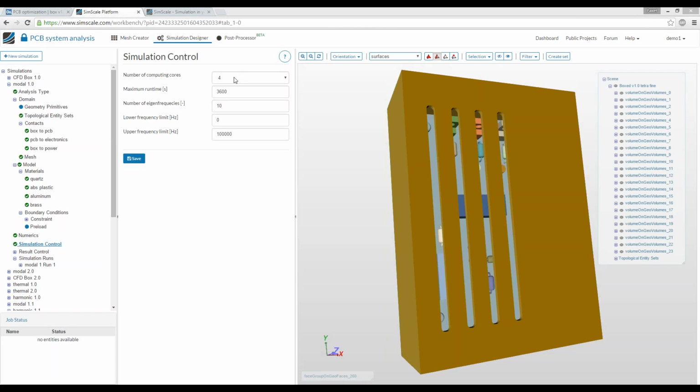What I like to think about whenever I select the amount of core hours is how big is the project. For smaller ones, it doesn't make sense to go with the maximum computational power. It would be as if we had people trying to dig a hole. If you put 32 workers to dig a small hole, instead of doing their job, they will be talking to each other. And that's exactly what's happening with the processors. They will be exchanging information instead of doing the calculation, and they will be waiting for the laziest guy or the one who has the most workload. In fact, the smaller the case, you can run it on smaller jobs. For modal analysis, the only limitation is the memory itself. And anyhow, the calculations will be performed on a single core because it's really, really fast.